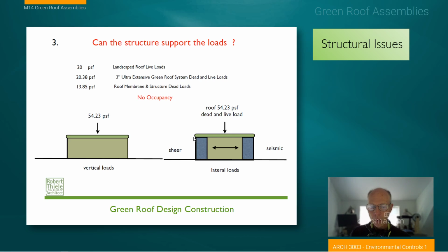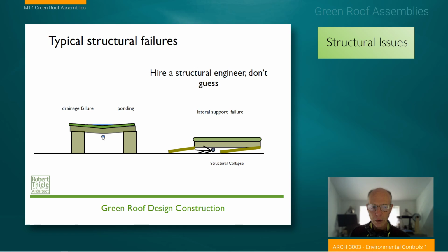So we have this potential for additional lateral loads through the building. We have a top-heavy type of structure, so we need to possibly look at additional shear capacity within our roof system. And our vertical loads are significant because of the issue of deflections and the migration of water in our roof system. So here we have both of those in kind of the failure mode.